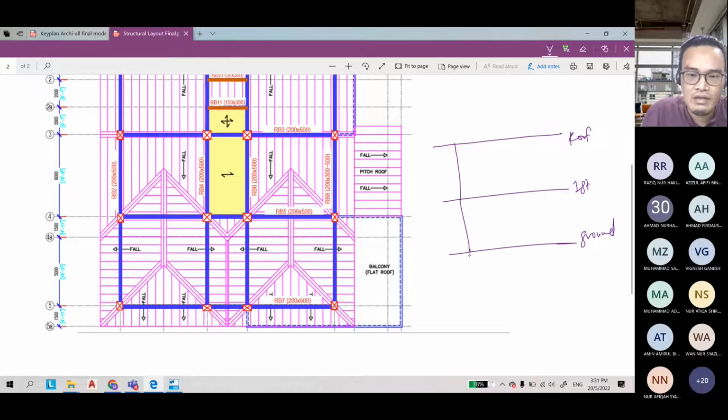So I want the stump. For the foundation, the stump is the short column under the ground. From the ground level to the top of the foundation is 1.2 meters. So we can provide piping later under the ground. This is your ground beam, so you can provide the piping, and the piping will not collide with the foundation. And then for the house, 3 meters is enough. This is also 3.0 meters.